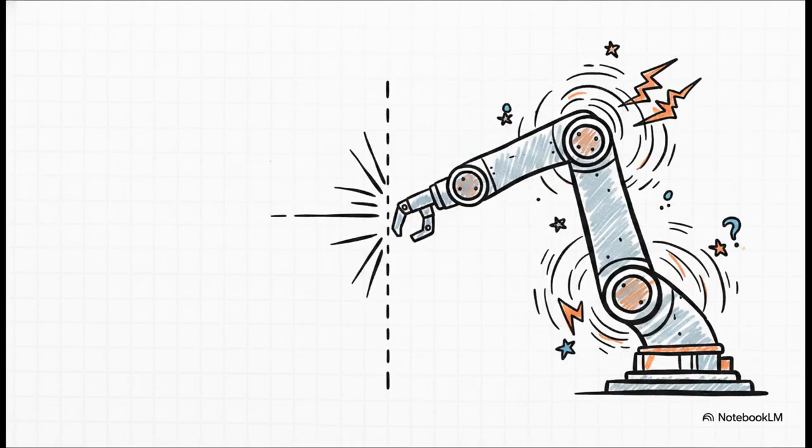Well, when a robot hits one of these unseen boundaries, you're going to see it exhibit some incredibly strange behaviors. You might see sudden, super jerky movements, or the tool center point, basically the business end of the robot, might dramatically slow down or just come to a grinding halt. In some extreme cases, its internal joint motors might simultaneously attempt to accelerate to their absolute maximum speed. The poor robot literally gets stuck trying to move through empty, unblocked air.